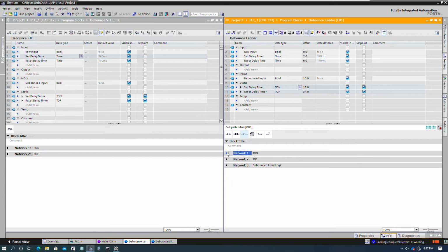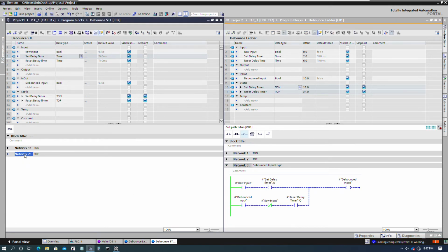Now comes the somewhat tricky part, the hardest part of this whole thing. Whenever you go to write this type of logic, just think of it in the name of the mnemonics and what you're logically doing. We are saying AND raw input. We're taking the RLO and the raw input, doing some Boolean expression, some Boolean math. So we're going to say AND raw input. And to help us remember, we'll put it over here.